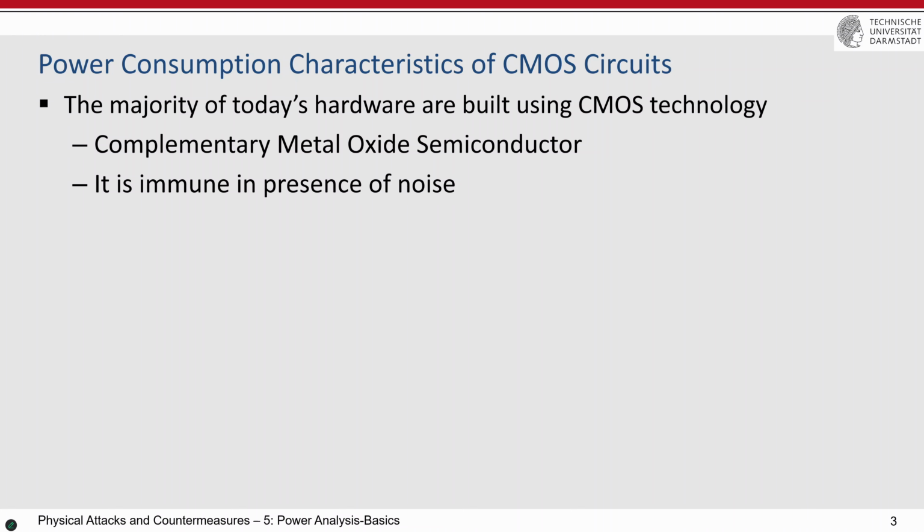0.5 or 0.7 or 0.8, whether this is considered as 1 or 0. And then the logical gates which work in this domain, for example AND gate, OR gate, XOR gate, receive the level of the voltage as the input, and then they produce the output also as a level of voltage. For example, if you have an AND gate with both inputs 0, meaning the voltages are close to 0, then the output should also be close to 0, not something higher, closer to 0.3 and so on.